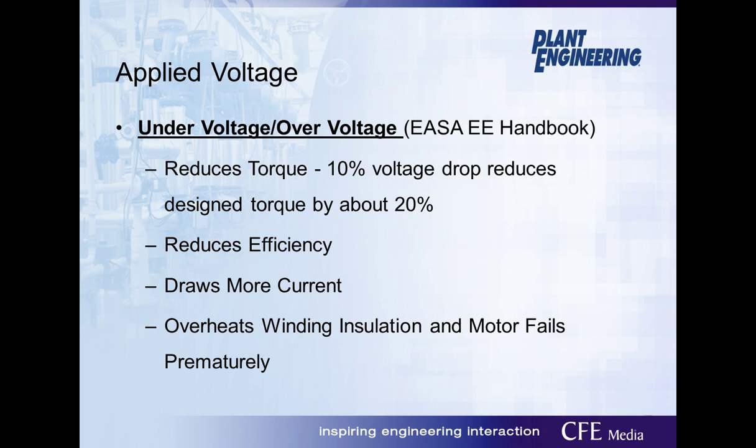So secondly, along with temperature, voltage is another force acting on the motor during operation. Always verify rated voltage on the motor nameplate. Sometimes you may have multiple voltages on the motor nameplate. Looking from personal experience, I can think back to an instance where a dual voltage rated motor was connected to a 480 volt supply, but was wired for 230 volt operation.